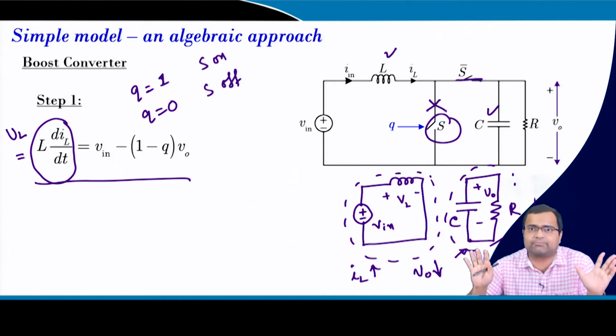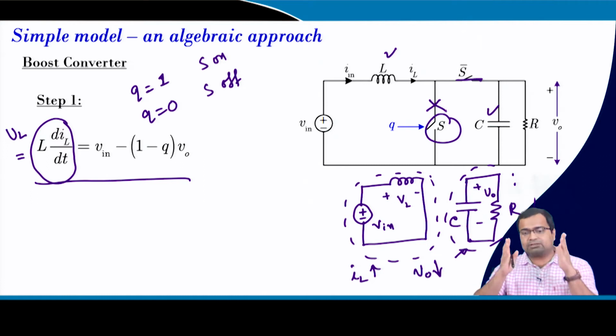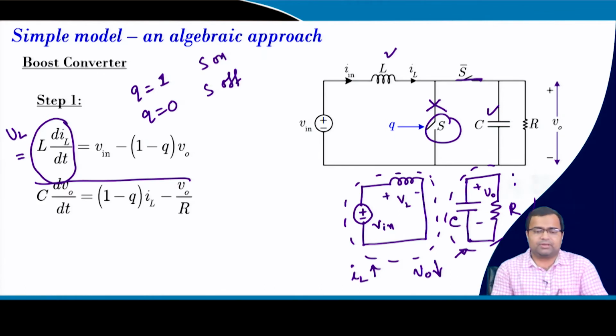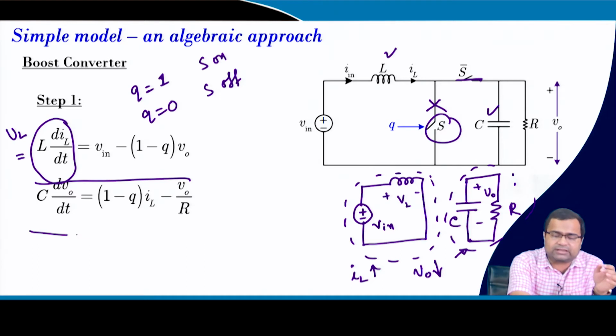So, you have to be very careful about the boost converter, and that is why in most commercial boost converter products we use current mode control, where we have direct control over current and we can limit the current and turn off the switch. Here the switch has a discontinuous mode. Similarly, you can work out the output voltage equation as I told.